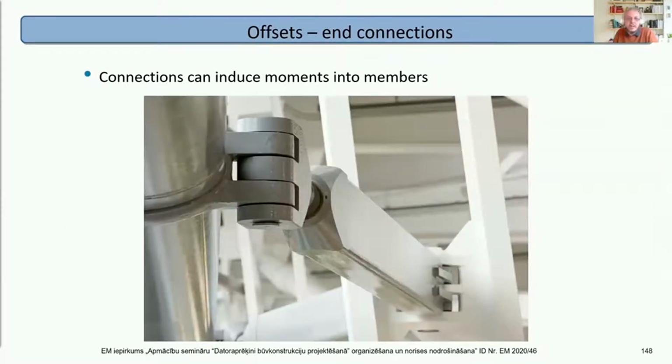Steelwork connections. So steelwork connections are often pinned, so they don't transfer moments, but the connections can induce moments. So here we have some connections. I think that was Heathrow Terminal 5. I can't remember. Anyway, you can see that there's these connections. There will be axial load in these connections, and because of the eccentricities, it will induce moments in the supporting members. And if there's moment being induced, then you've got to make sure that is designed for.